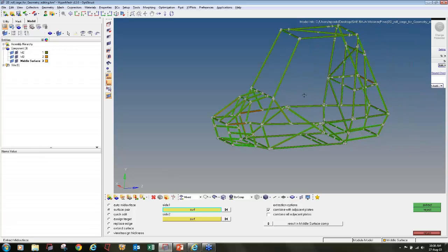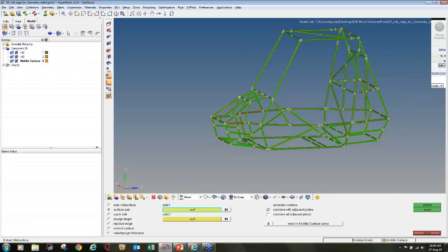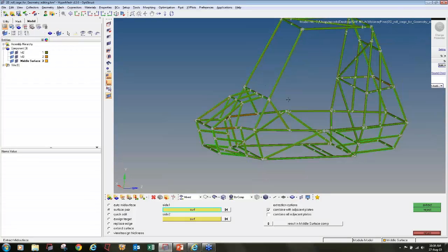It is not about getting the results at any cost. CAE is all about getting more accurate results. So for getting a more accurate result, you have to follow a process which is accurate. While you import a geometry, you have to see whether all the pipes are properly connected or not. If not, you have to connect them and then do the meshing.